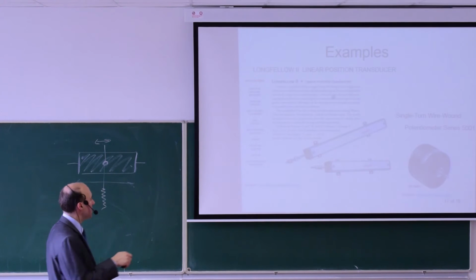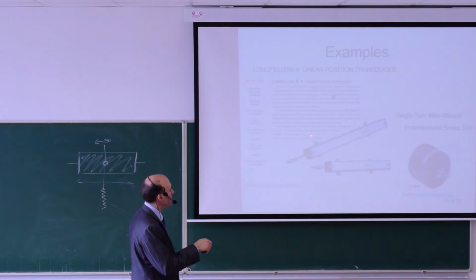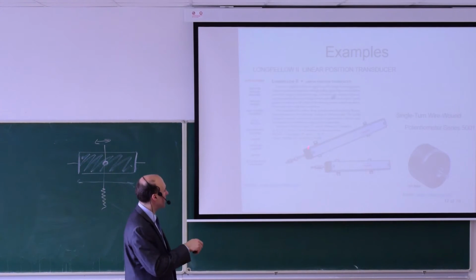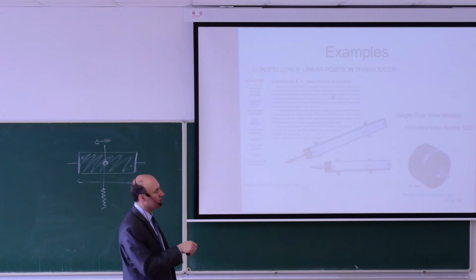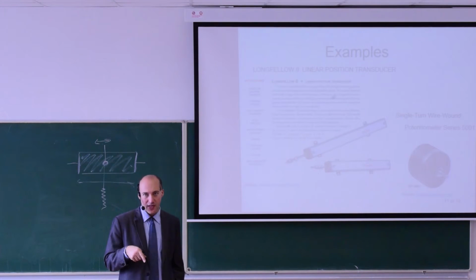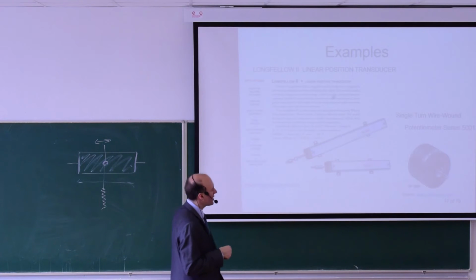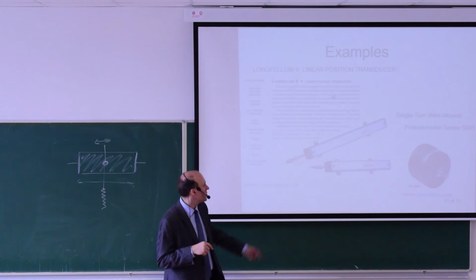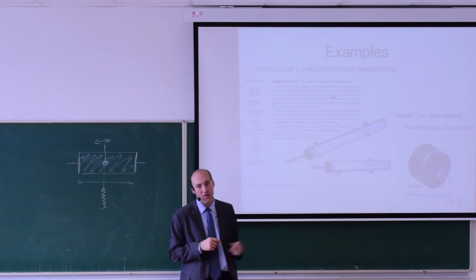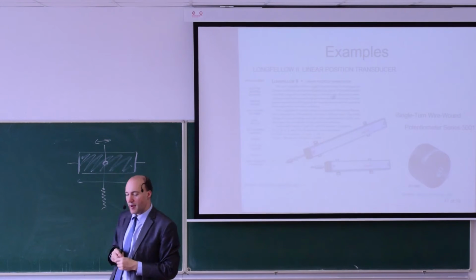In all cases, you will find something like this. For another example, they say maximum voltage is 30 volts. The reason is that I need to limit current going through the sensor. Here you see 100 milliamperes is the maximal current.